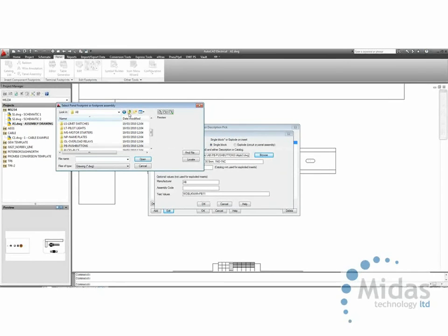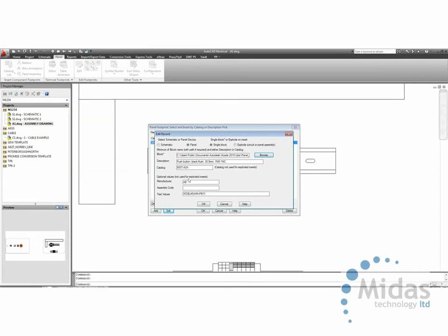So all that is browse into panel metric, Allen Bradley, push buttons, and APB3.dwg. So this is the symbol I want to insert. You'll also notice that the manufacturer has been defined, but also the WD block name is going to equal PB11.